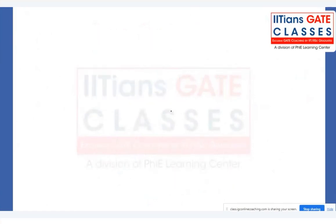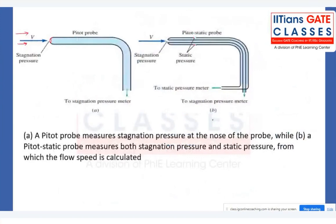So I think it is clear when we can apply this static law and when we cannot. Now, all of you just tell me whether it is clear or not. Whatever the circumferential hole is there, that is not for the stagnation pressure measurement. That is only there for the static measurement. Yes or no? It is just like a piezometer tube, where the tube is there like this, and the flow is happening inside the tube perpendicular to the streamlines. It is also happening like this.